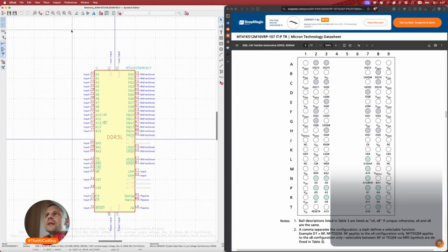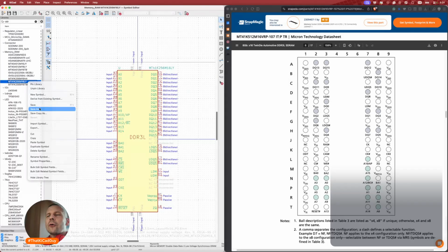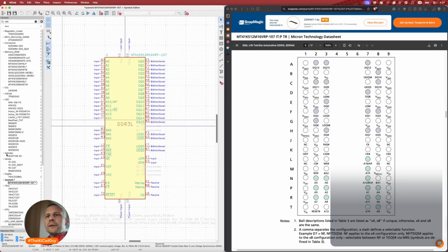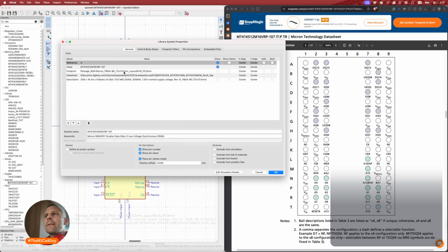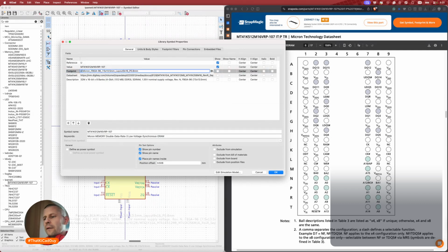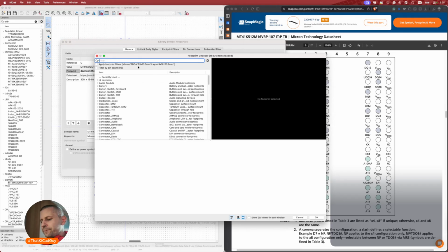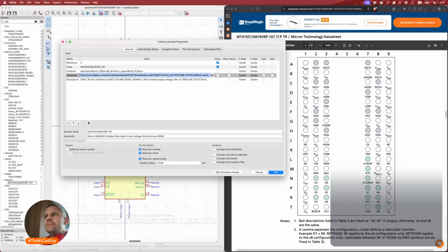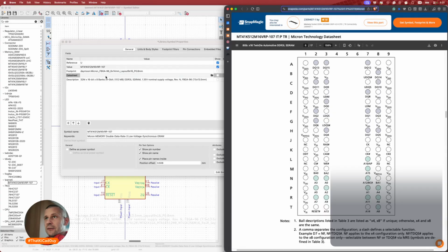So I can copy this into my library, of course, under the correct part number. Here it is. It even links... no, incorrect. Here is an incorrect library, so I have to assign this one. Yeah, this one was checked, 8 by 14 with the strange layout numbers here, but the pitch is the same, and I checked the dimensions are correct. They say that the datasheet link has the correct datasheet, but last time I checked, it doesn't.